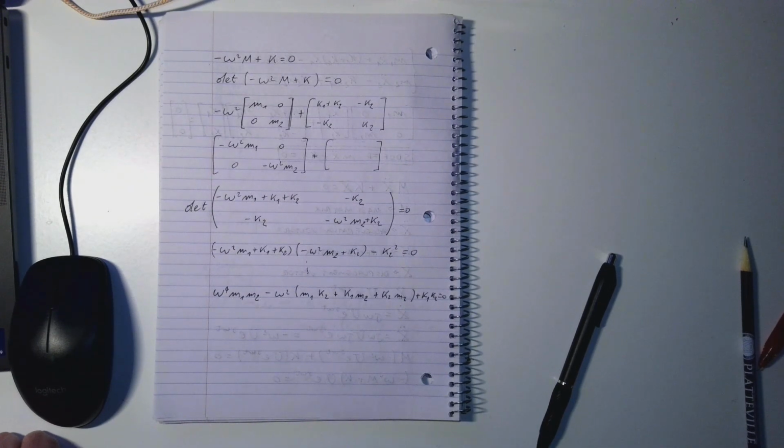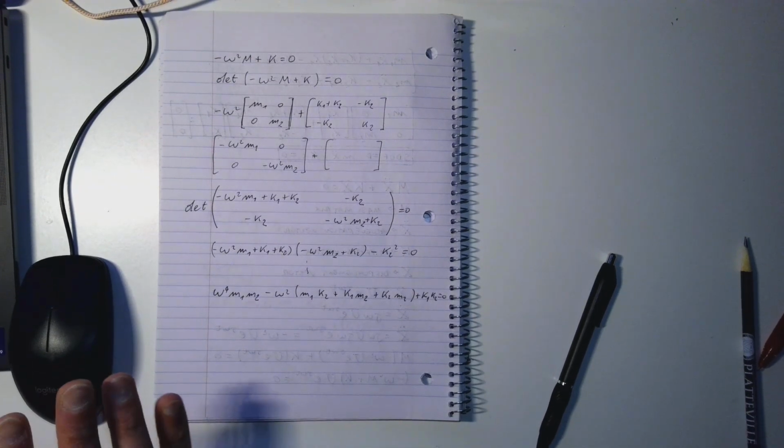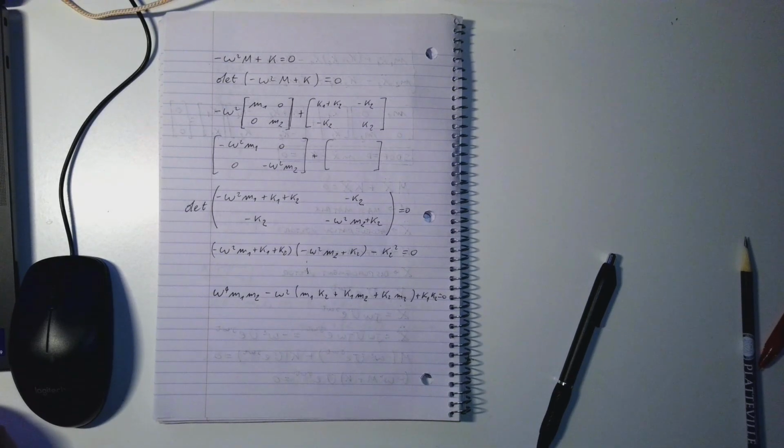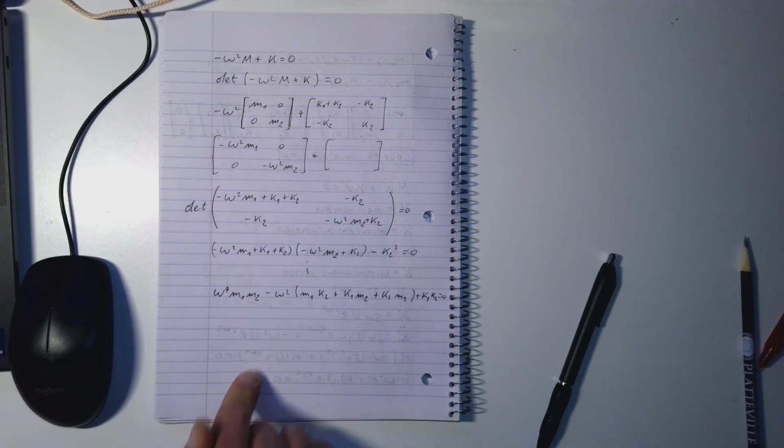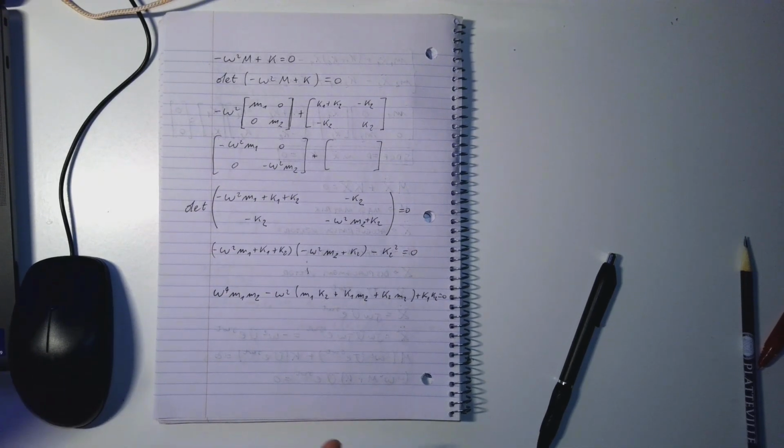Even if we find the first natural frequency, the second natural frequency, and then the third, the fourth, this doesn't mean that the first mass oscillates with the first natural frequency and the second mass oscillates with the second natural frequency. Because these are natural frequencies of the system, and all the masses together oscillate at all natural frequencies,